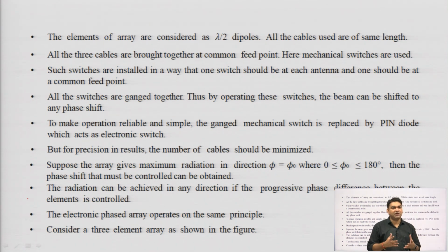Such mechanical switches are installed in a way that one switch is at each antenna and one switch is at the common feed point. In an antenna array system, the feed point is the point from where we can excite the individual element, and the feed system and the current through which the element is excited determine the phase.